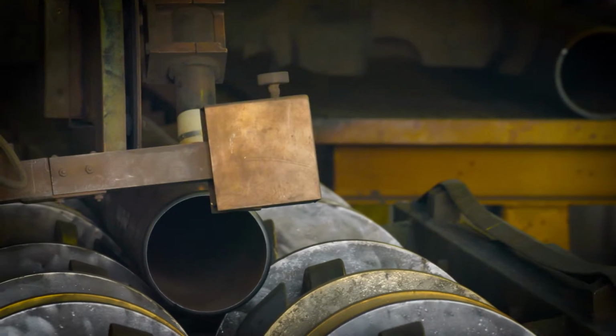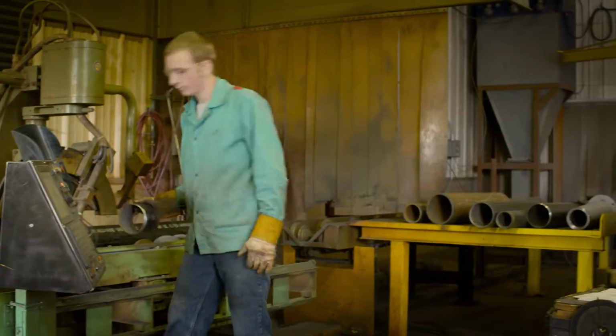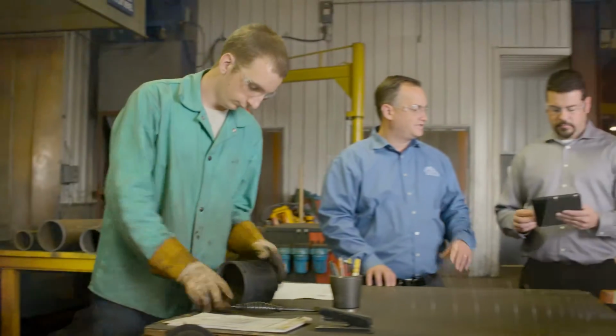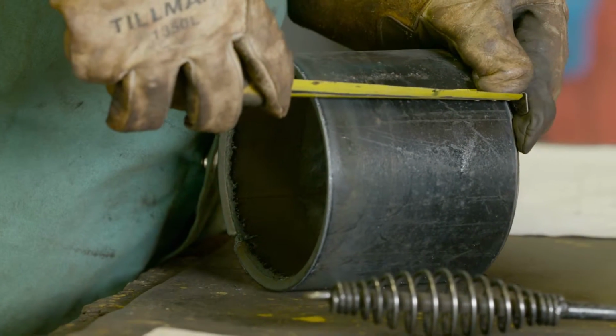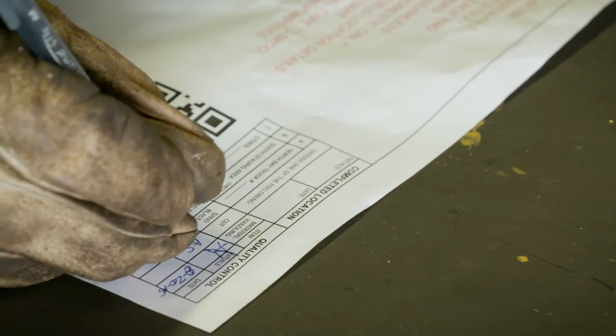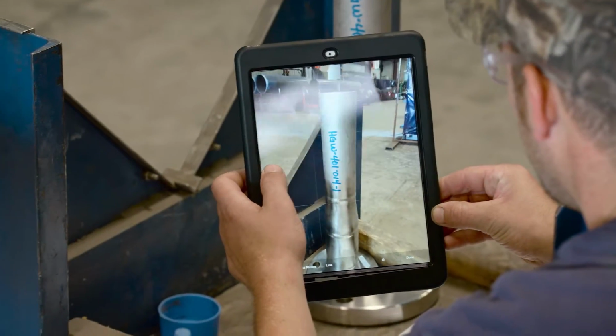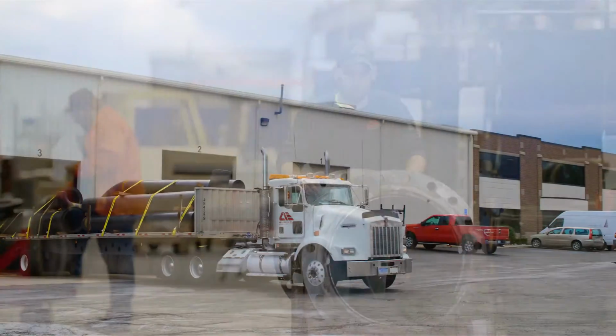Fittings and pipe is gathered together, then goes through the tacking process, through the welding process. Each stage of that is captured with BIM 360 Field. We use that record to verify that each quality component has been met. So each individual in the process step is signing off a portion of the drawing. Once we pass through that final stage, we're free to load it upon the truck and ship to the site.